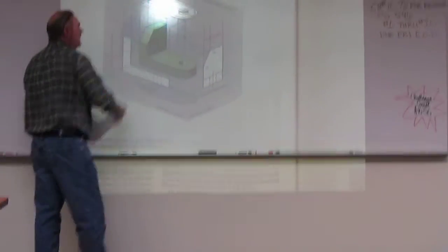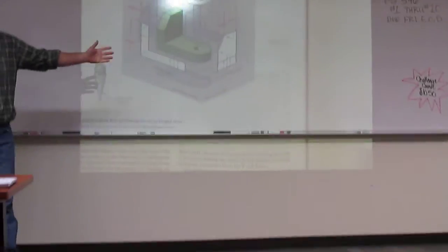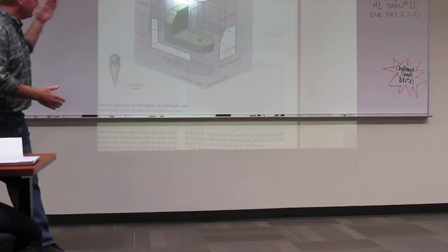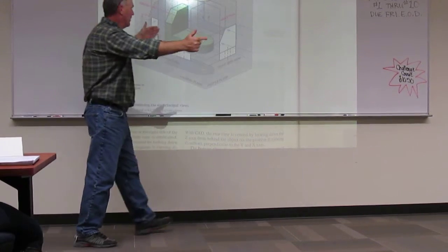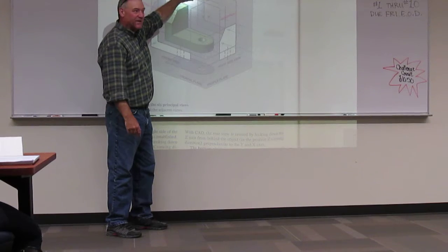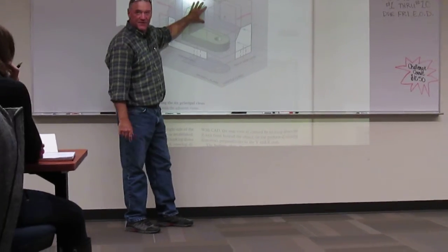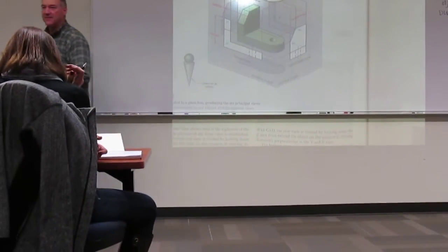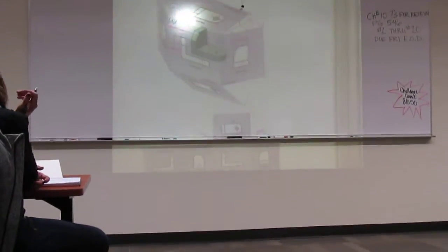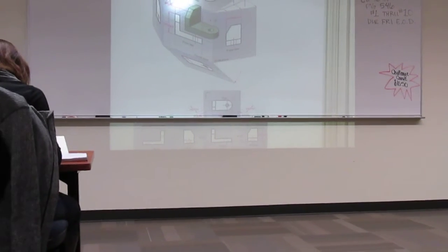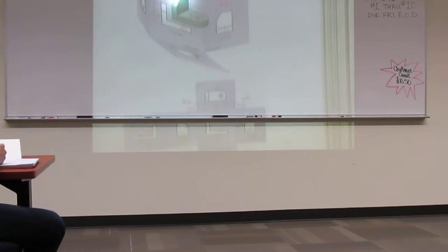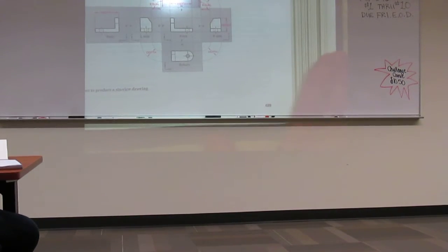Now, once we have this little glass cube that's imaginary, we've encompassed the object. We as a reader have sat here in the front at infinity and projected onto this view, and then we rotated to the right and projected here, got on an airplane, looked down on it, and projected this view. We get all of these views etched into these glass boxes. We then unfold the glass box to create what we call a six-view drawing. This is on the next page, and they kind of show you the process, where here they're starting to unfold the box and they put it into its final configuration down here at the bottom.